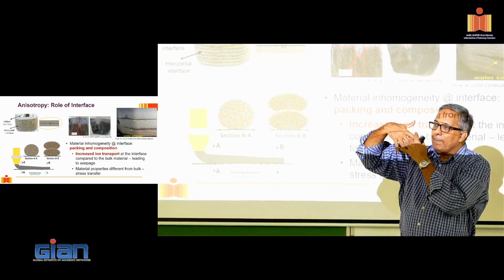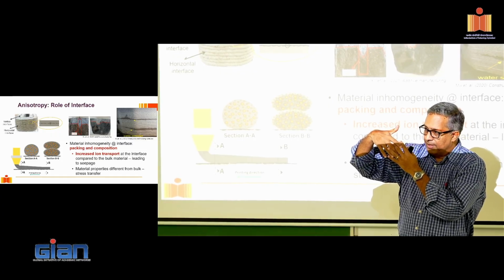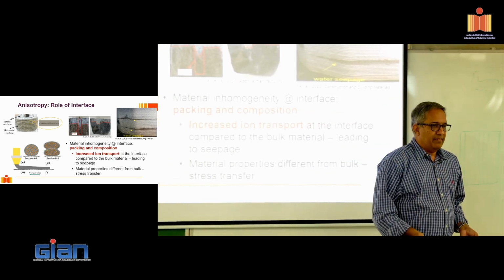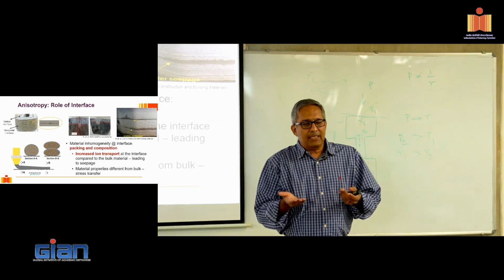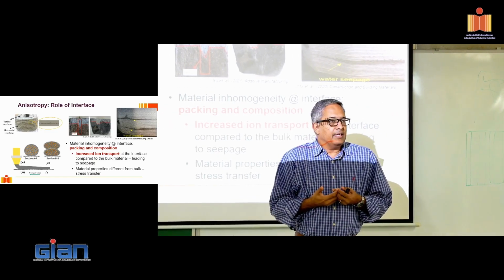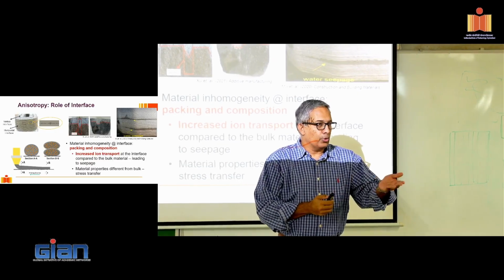Is there some miscibility of the paste that's happening? Is there some ion transfer that's happening? So what kind of mechanisms are active here? We still don't know, but essentially some kind of a bond develops there. And maybe at some level, we can think of the mechanism as similar to what we would have when we place fresh concrete against some old concrete, like a cold joint.